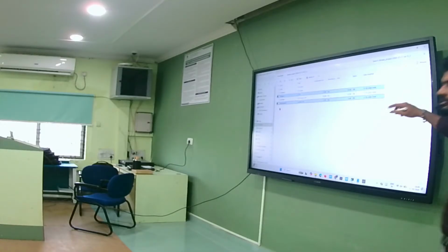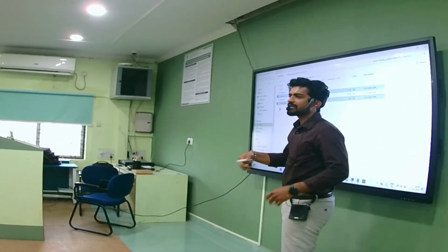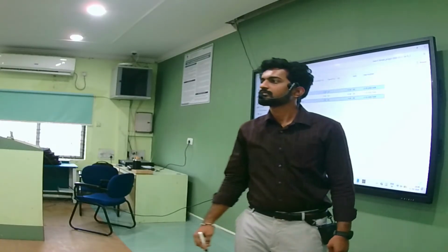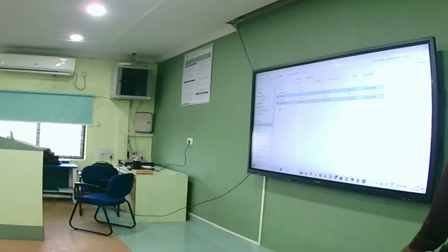We have to add these two files. Okay, this nano_ai.h we can add in the INC folder. But where will we add this .a library file? At that time we have to create one lib folder. Okay, so that's a simple step here.